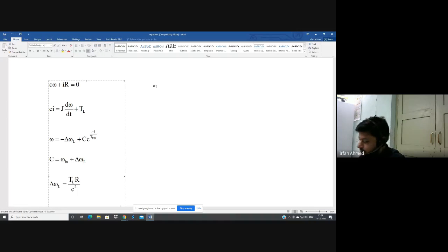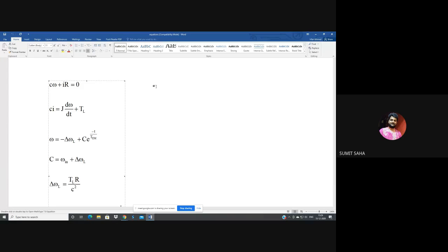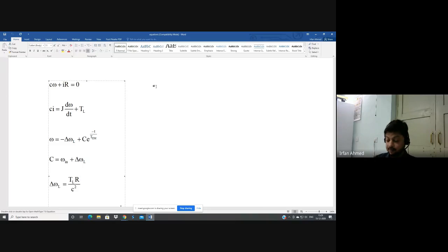Okay. So these are the equations for dynamic braking under primary transient conditions during dynamic braking or static braking. We have already seen how to obtain dynamic braking in case of a DC shunt motor. The field winding supply is maintained constant so that the flux remains constant, and the armature winding is disconnected from the supply and connected across a braking resistor.